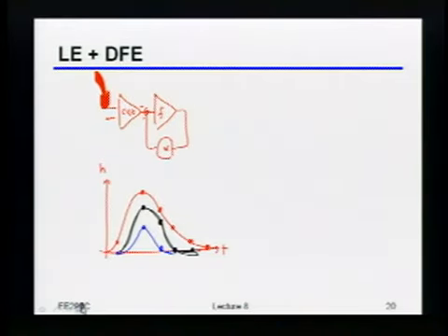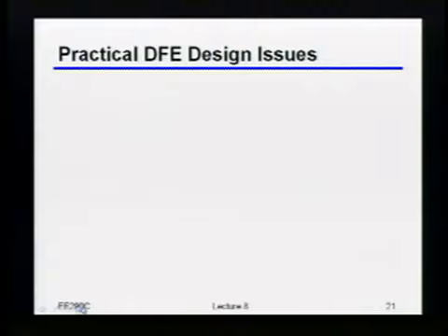Okay, so unless there are more questions on this, the next thing I just wanted to briefly mention is, in the context of the receive FIR filters, we talked about how sometimes you end up wanting to interleave those things. It turns out if you're operating at pretty high bit rates, sometimes you end up wanting to interleave the comparators as well, because it gives you more time to make the decision, or to resettle the comparator after making the decision, meaning to precharge back to the nominal state.